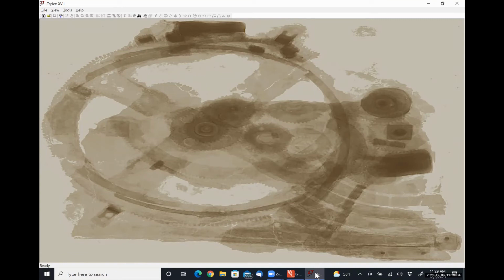Okay, yeah, sure. So if you had a 5-volt supply and you wanted to make VCC something other than 5 volts, yeah, absolutely. You could use some sort of voltage divider circuit or something like that. The thing that you would have to worry about there are what the loading effects are going to be on your voltage divider circuit. And we'll talk a little bit about something kind of like that in just a minute with generating reference voltages as portions of VCC.